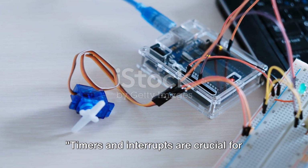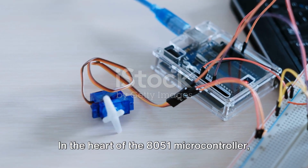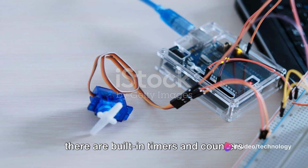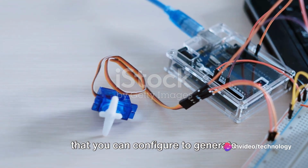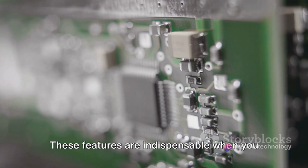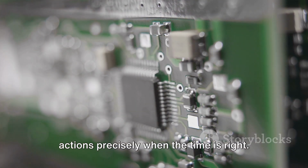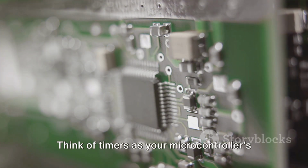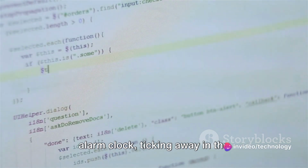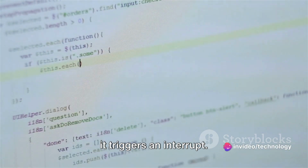Timers and interrupts are crucial for time-sensitive tasks. In the heart of the 8051 microcontroller, there are built-in timers and counters that you can configure to generate interrupts at specific intervals. These features are indispensable when you need your program to perform certain actions precisely when the time is right. Think of timers as your microcontroller's alarm clock, ticking away in the background, and when the alarm goes off, it triggers an interrupt.